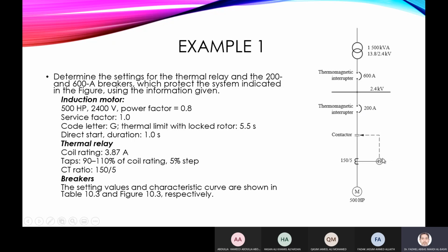contactor during short circuit? The problem here is the contactor is not designed to break high short circuit current. It will get damaged. So if you have a relay that senses a fault in the motor and tries to give a command to a contactor to open, the contactor will get damaged. By manufacturer, most contactors by standard are designed to break up to 10 times its rated current.